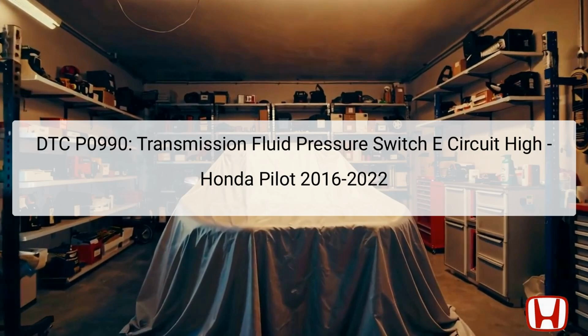The diagnostic trouble code DTC P0990 indicates a high circuit fault associated with the transmission fluid pressure switch E, specifically for the 6th clutch. When this fault is detected, the powertrain control module, PCM, enforces a fail-safe mode, restricting the transmission from shifting into any gear other than 3rd or 6th. This mechanism is crucial for preventing potential damage to the vehicle's transmission system.